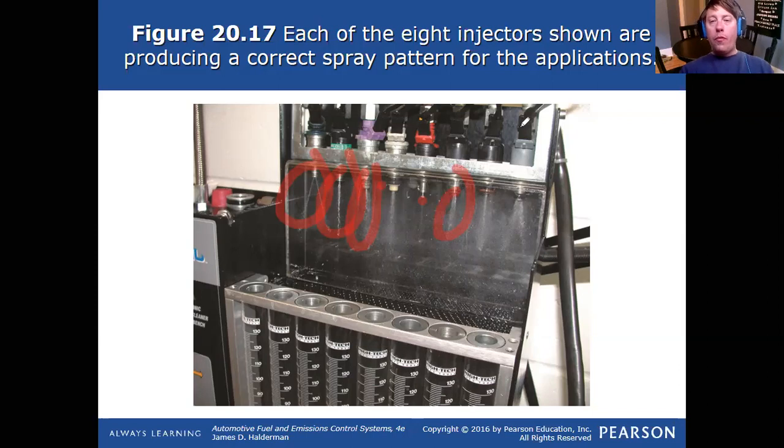So when fuel leaves the injector, it has to leave in a mist, a fog. Maybe I'll include a couple of videos I have saved on YouTube, looking at the fuel flow of these injectors, bench testing them. The fuel has to leave the injector in a mist, it has to atomize, poof. If it comes out in a jet or in droplet form, that's liquid. Fuel cannot burn if it's liquid. It has to be atomized into a fog, a mist.